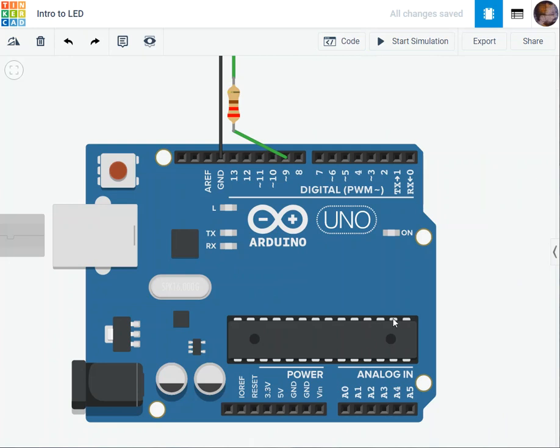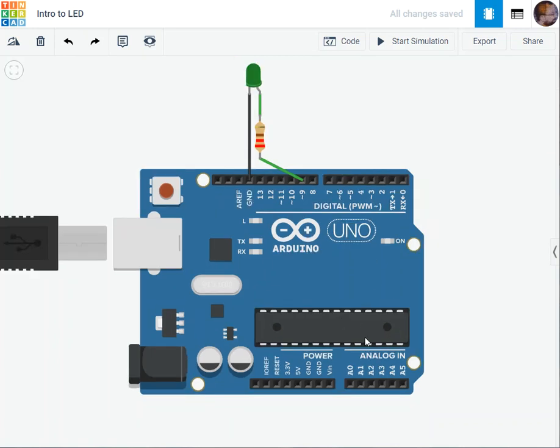We have to be careful not to damage this microcontroller. It could be damaged if we overload the board. Let's say I have only 5 volts and I'm connecting something to the board that needs more than 5 volts. This might damage the pin, or might end up burning your chip, or the chip gets static if you touch it from the back and it's not well protected. Depending on your circumstances, you might burn the chip. So this microcontroller is the main part of the Arduino.